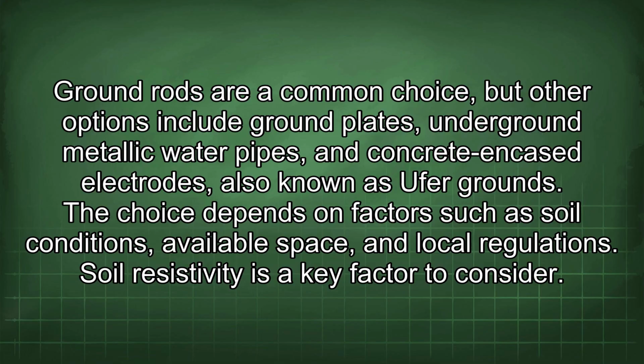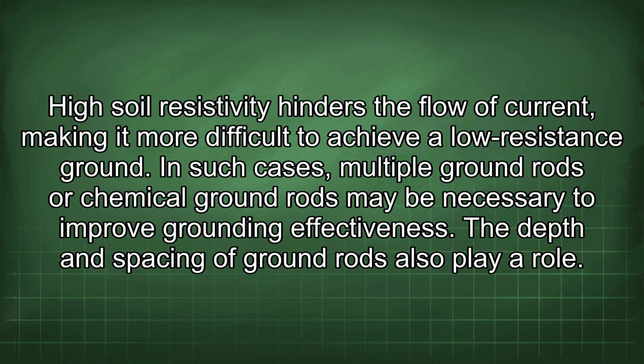Soil resistivity is a key factor to consider. High soil resistivity hinders the flow of current, making it more difficult to achieve a low resistance ground. In such cases, multiple ground rods or chemical ground rods may be necessary to improve grounding effectiveness.